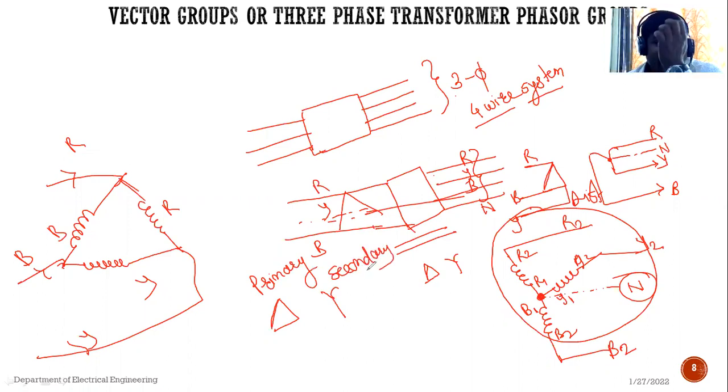We connect the primary side in delta and the secondary side in star, because otherwise we would require a 4-wire supply on the input side; to reduce the conductor cost, we generally take 3 conductors from the mains, and this delta connected transformer primary can be converted into a star connected secondary. So that we get a 4-wire. We can get the 4-wire from that.